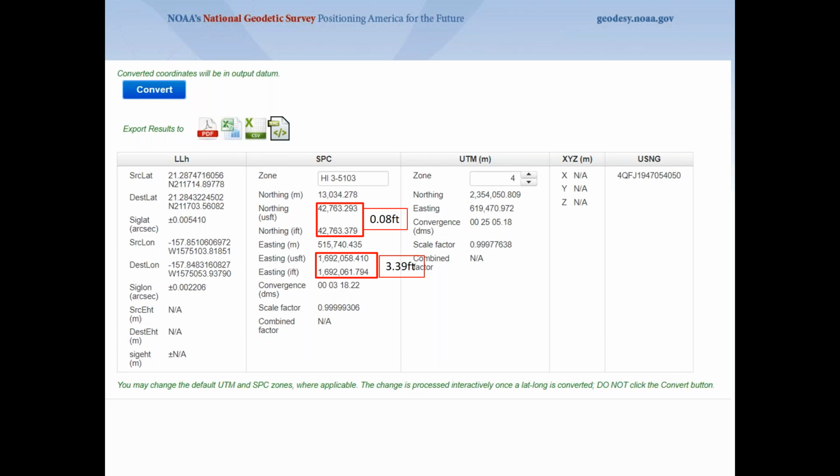And when I converted things back, I just tried, okay, I'll take the feet converted back to meters, because we knew we had common points, to see what the meter value was, and I knew they used state plane coordinates and what theirs was. And what I found out is that the GIS that the airports had given the contractor was done in international feet, not survey feet.